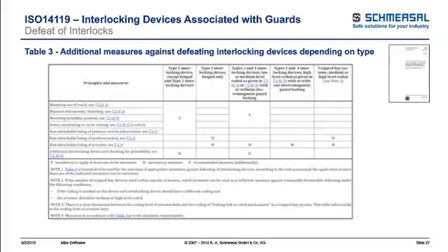So when you use non-detachable fixing on position switches, if we look at a Type 1 device, whether you're using mounting out of reach, at least one of those is required with the X on there, and it's also recommended to put additional interlocking devices on there. We'll give you an example.